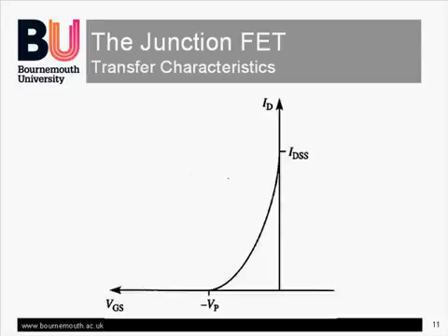This slide shows the relationship of the output drain current to the input gate voltage. That is, it shows the gain of the device, or rather its transconductance, as we're talking here of a current output with the voltage input. Provided the FET is in its saturation region, we needn't worry about the drain voltage, as it won't affect the output very much, but the gate will.